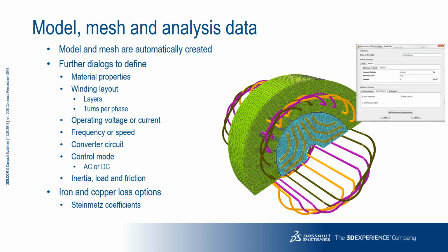Following this, the geometric model and the mesh are created automatically. The mesh size is calculated automatically, but the user has the chance to override the default setting to either perform a quick coarse analysis or to define a fine high-resolution mesh for final detailed checking.